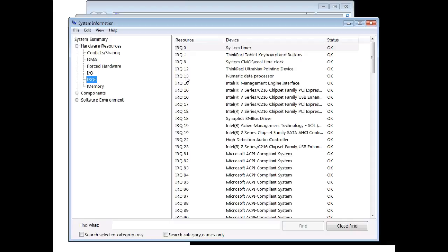What it does is we have one interrupt pin on the processor, and all the interrupts come into the priority encoder. And the priority encoder sets the priority. Does that make sense? So that's a situation where we would look at a priority encoder. So look at everything that generates an interrupt. This computer never scans the keyboard unless you do what? Yeah, and this would be like you raising your hand. That's the way most classrooms go, or you speak out in my class, but you interrupt me, and sometimes I finish what I'm doing. So it depends. Most of the time, it'll finish the current instruction before it honors the interrupt.